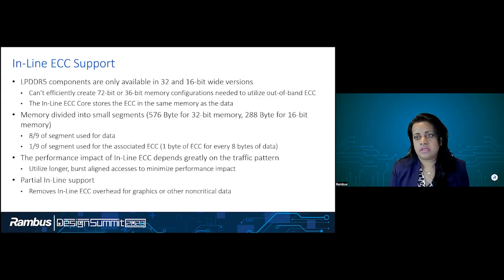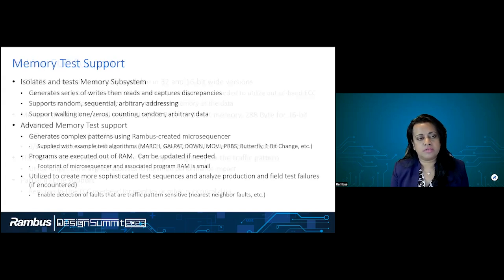So with that, let us go ahead and take a look at the memory test support that we offer as part of our solution offering. As we previously talked about, we do provide pretty comprehensive memory test support to help our customers in the bring-up phase of their design. As part of the memory test support, we provide some basic writes and reads to capture discrepancies, and it supports random, sequential, arbitrary addressing, and also walking ones, zeros, counting, random, and arbitrary data as well.